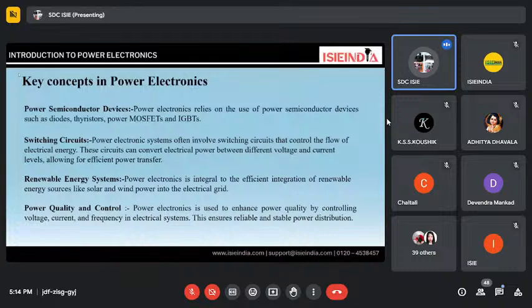Along with increasing and decreasing, we can regulate the speed and voltage variations, like with a throttle. In the throttle we also have a linear Hall effect sensor, not a bipolar one. It's a linear Hall effect sensor. With the movement, at a particular angle, we have a magnet in it, and according to the magnet, we see the voltage fluctuation. That voltage fluctuation can improve the quality and control. We are getting proper quality, and we are not getting any unbalanced output. We are getting a balanced output. Along with that, we have full command over it.